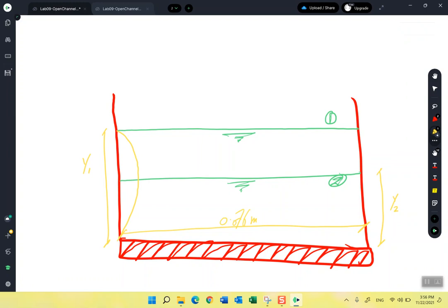That's right, because it is related to the material, and because we have 2 different materials, the Manning coefficient will depend on the material and also the condition of the water level. If you have 3 sides with the same material, regardless of the position of the water, it will always be the same Manning, because the same water is touching the same material.